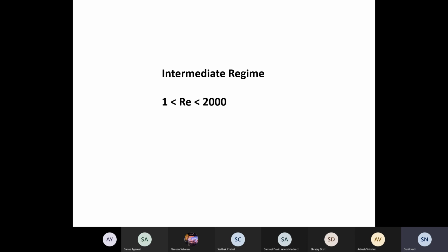The same thing, if you were to assume a constancy of the CD, as you do for the Newton's turbulent flow regime, Newtonian region, where Newton's law type thing applies, I would not advocate that either for the intermediate region between Reynolds number 1 and 2000.